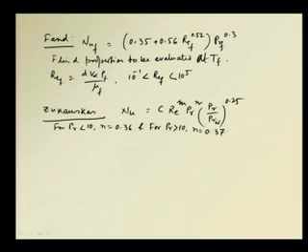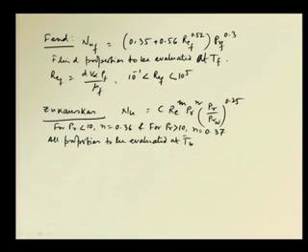These are minor changes, but all properties are to be evaluated at T_B, the average bulk temperature, except Pr_W, which is at wall temperature.